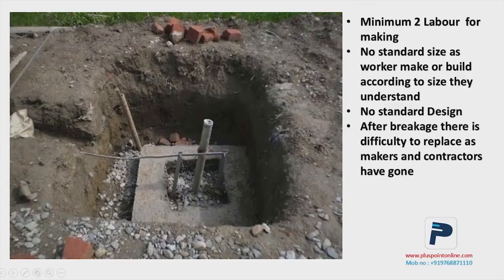While talking about brick earthing, there is no standardized process for this as well. The labor used to install the plate earthing and then build the brick wall around it is usually uneducated and also costly, especially during this period of lockdown where labor isn't really available. Also, since there is no standard process to install this type of earthing, the chances of it getting spoiled early are also high. In 1-2 years, bricks can also get destroyed under the ground.